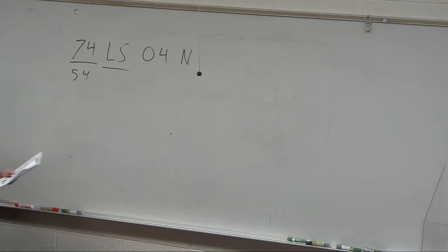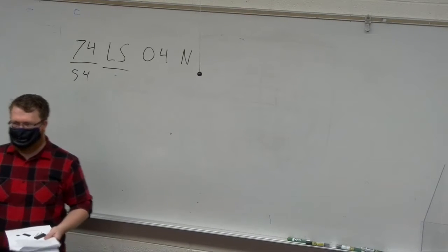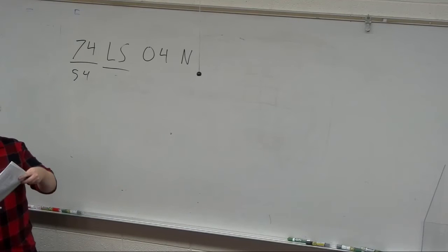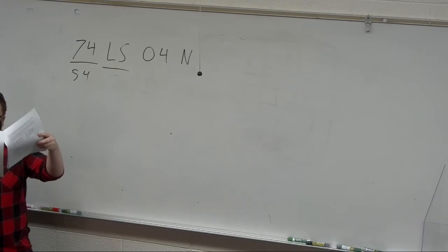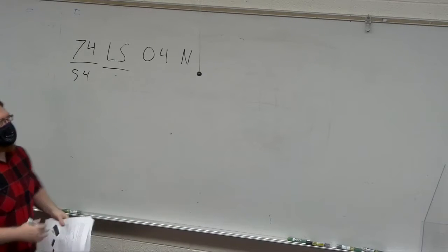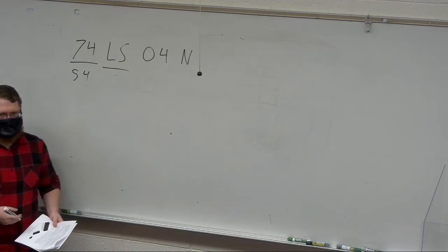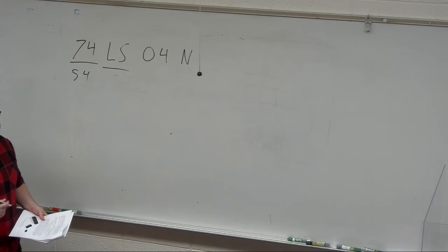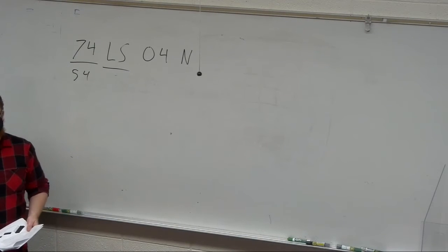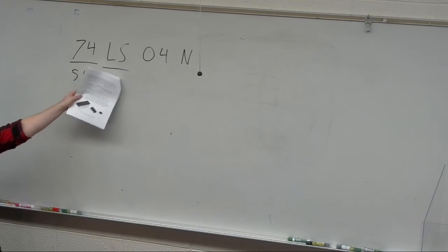The LS is the logic family. So the same company might make multiple chips with different logic families. If you pulled up your chapter 6, there's this nice little table, and the LS family is the low power Schottky logic. All that's saying is what type of logic it is. Is it 5 volt, 3.3 volt? There's usually some attached speed limitations to it. Some of them will have assumptions of active high versus active low. So that's all the LS is saying, its type.